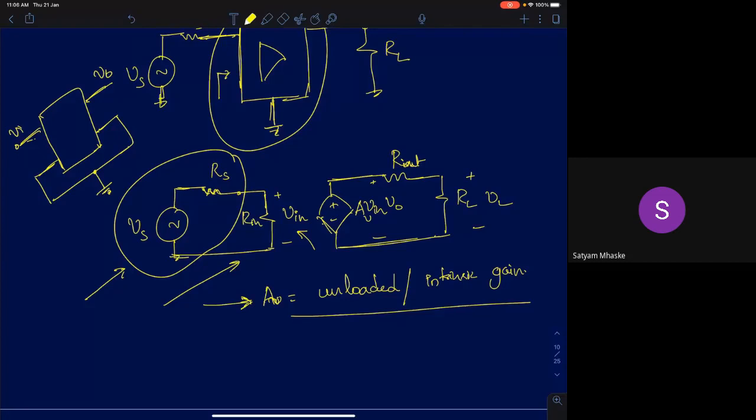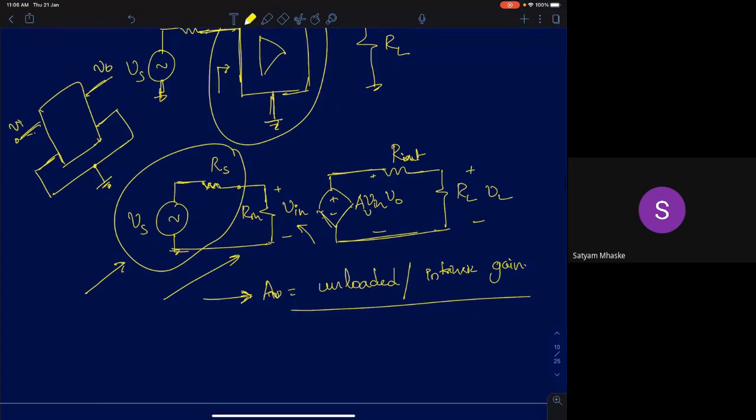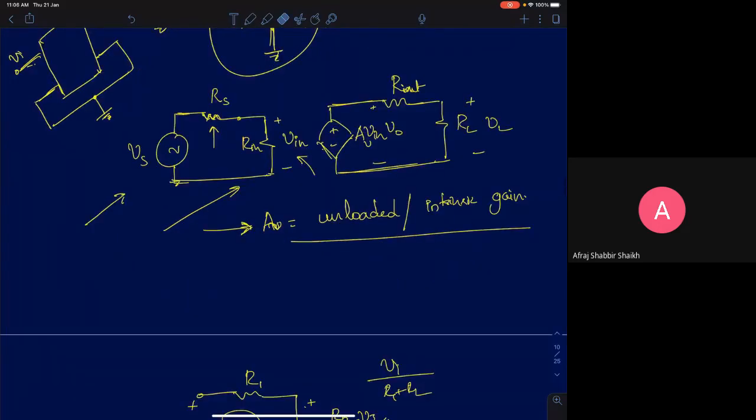That's your voltage source. So we discussed why do we actually model a resistance in series with the voltage source? What was the reasoning? What does the series resistance capture? What does the series resistance and a voltage source capture? Internal resistance. Yeah, internal resistance, and more, what does that signify? When I model it this way, does it make the model more practical? How do you quantify? Internal resistance is fine. Is there something more than that?